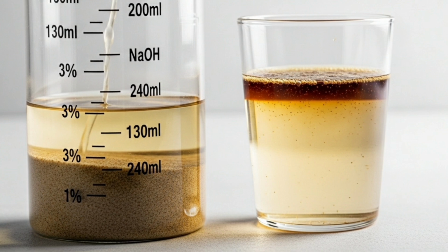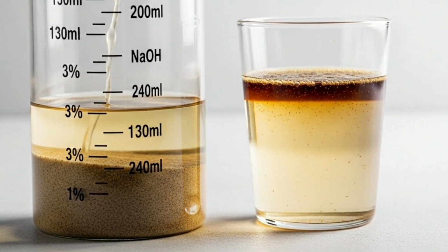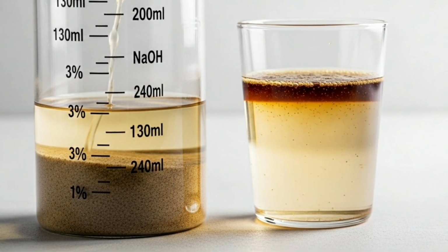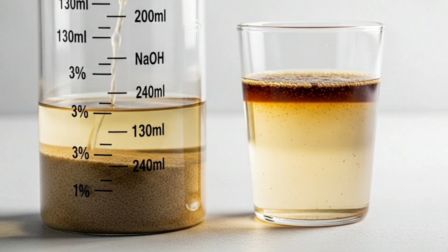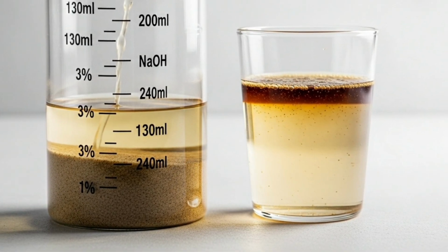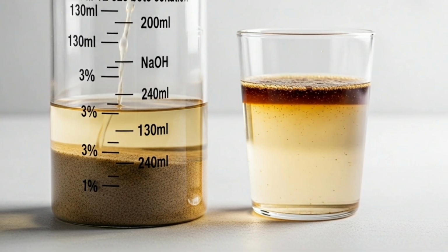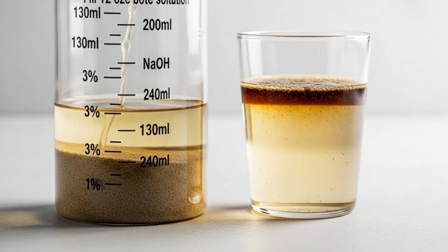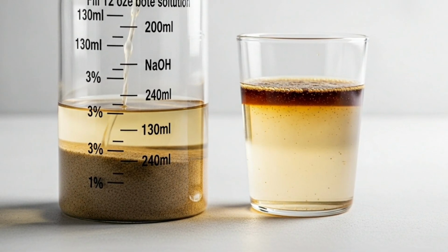If the liquid is colorless or has a light straw yellow color, the sand is acceptable. If the color is a deep brown or dark, it indicates a significant presence of organic impurities, and the sand should be rejected or washed thoroughly. This test prevents one of the most baffling field problems: concrete that just won't set.